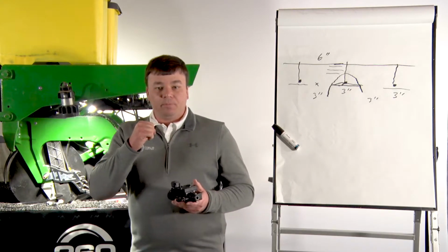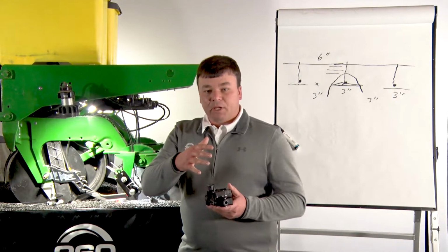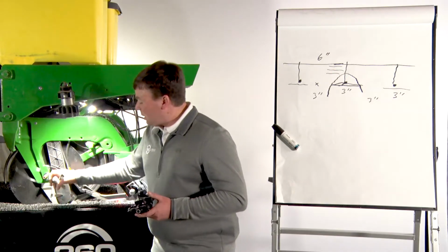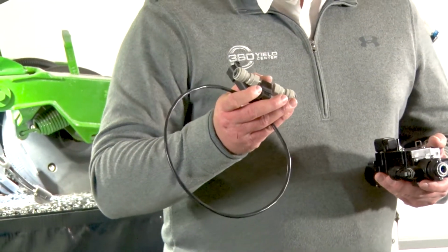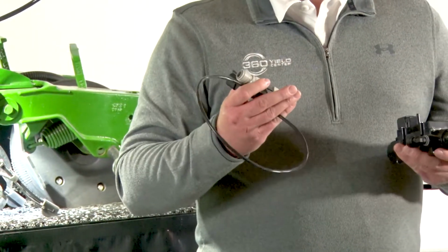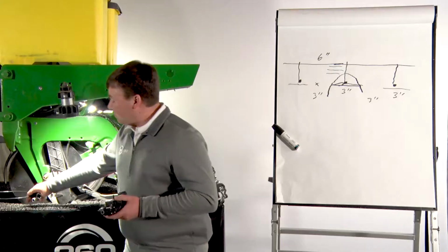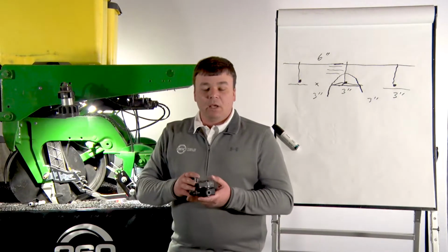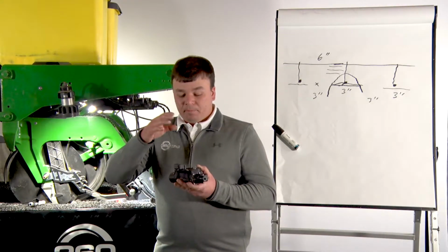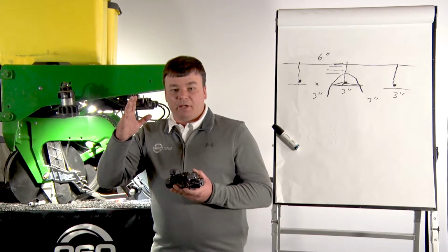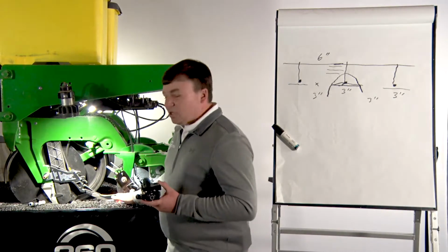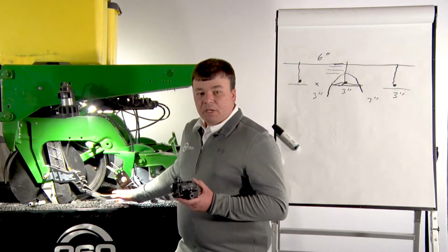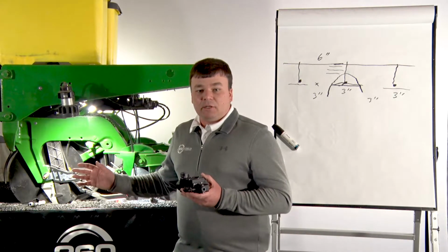We pull the valve open. The amount we pull it open is then adjusted by our flow meter. So we're measuring the flow that's passing through the valve anytime it's open, and we're looking at what rate you've told us you want to apply and making sure we've opened the valve to the right place to get that rate. We continue to move the planter ahead. The valve stays open as we create that dash on the ground. We reach the end, shut the valve quickly, flow stops on the end of your applicator, and we move on waiting for that next seed.